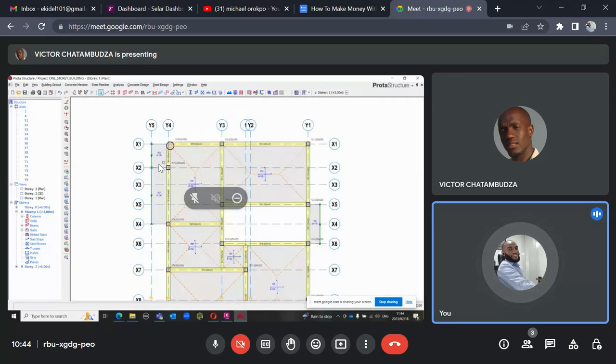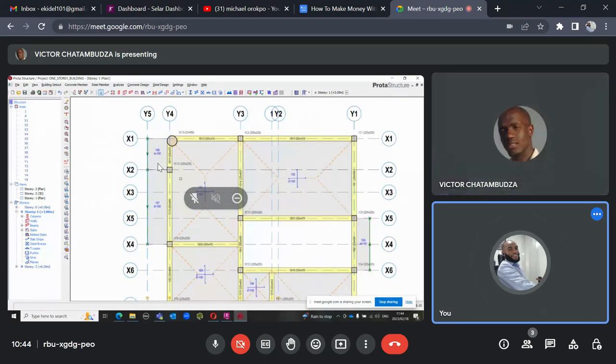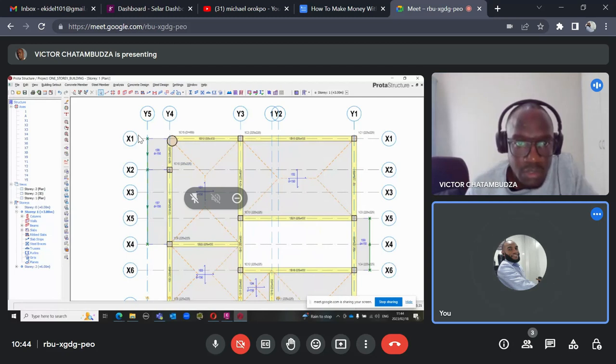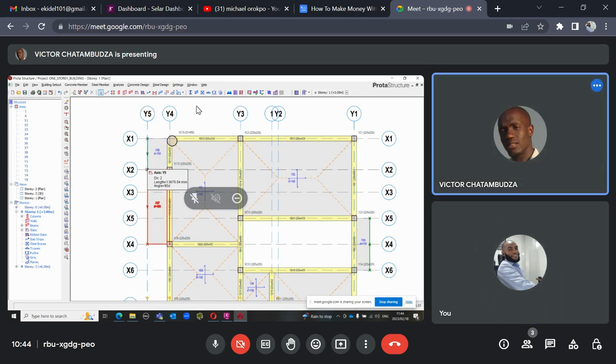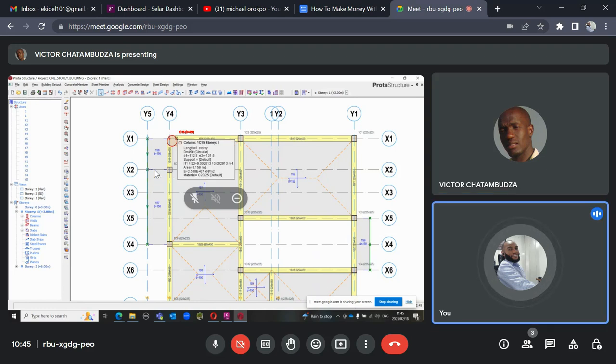So we are going to provide a cantilever beam from this point, from the X1. We can choose that X1, that point there. That X line from the circular column, right now. Let's put a cantilever beam there. Yes, from there. Can you hear me? Is it from here to here? No, it's from here to here, right? Okay, so let us put from this X2 a cantilever beam to carry the new column that we will put there.